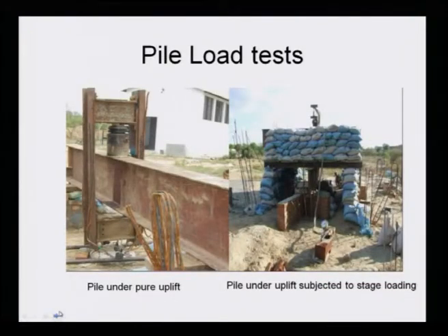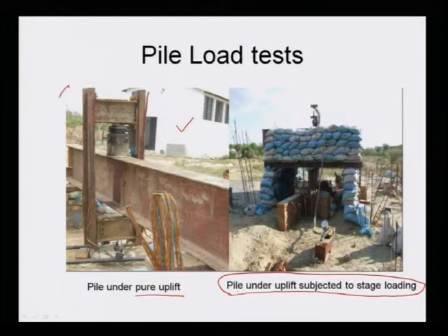This is another typical arrangement. That arrangement was pile load test with a compressive load. This is a typical arrangement for a pile load test to get its tensile capacity or uplift capacity. This is a pile under simultaneous uplift as well as compression capacity. How can this test be performed? If you look here, this is specially designed at IIT Kanpur in this workshop, so that we can measure load versus uplift capacity of the pile.